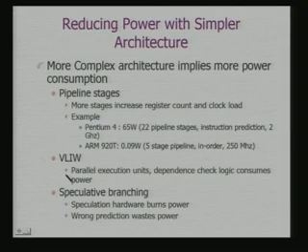Another example is VLIW. You have parallel execution units and dependence logic consumes power. So, although VLIW is used in the context of DSPs, there also power consumption becomes an issue. But here the advantage is very straightforward. If you can execute multiple instructions in parallel, then the total time taken will be less. So, total energy consumption can be less, although you may consume more power per instruction.